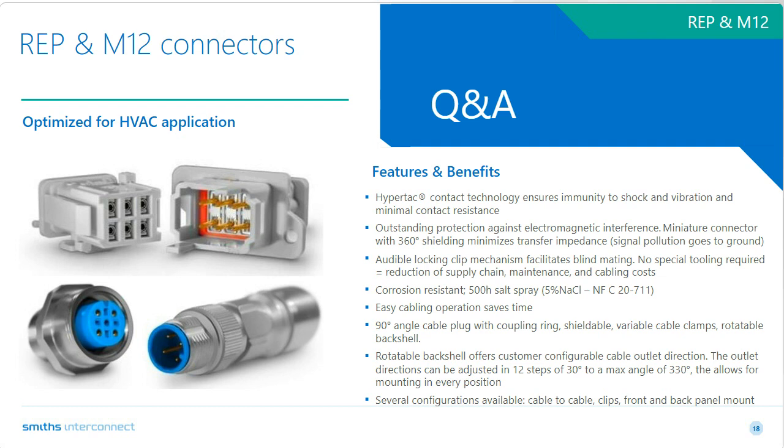And worse comes to worst, that localized heating can ultimately affect your insulator, and from a failure mode analysis perspective, it can bring your whole system to a stop. So hence it is important that something as simple as an ingress rating specification, if you really follow the thread of failure mode, can ultimately contribute to a complete system coming to a stop or an inefficient system. So hence, Katie, it's so very important to have a connector which has got good ingress protection.